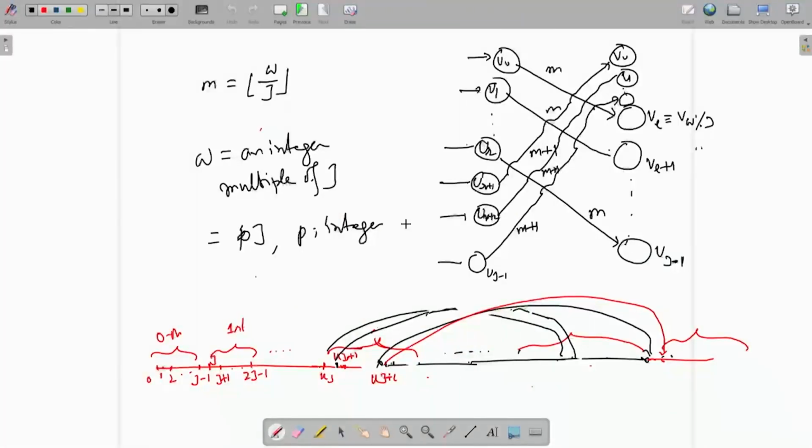Okay, so in the last class we started with unfolding, that is parallel processing. We considered the example of an IIR filter. We first gave you the general idea of parallel processing, that if you are ready to increase the hardware by j times, then you can increase the input output clock speed by j, or you can reduce the period by j, make it shorter. If the system is working at a clock period capital T, your input output clock period can be T by j.